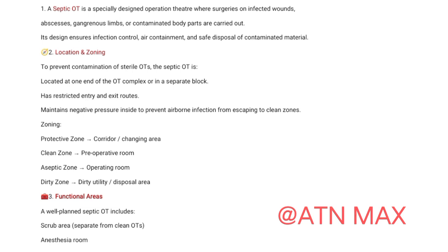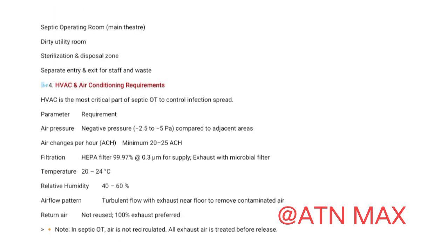Functional areas. A well-planned septic OT includes a scrub area separate from clean OTs, an anesthesia room, the septic operating room, which is the main theater, a dirty utility room, and a sterilization and disposal zone, with separate entry and exit for staff and waste.